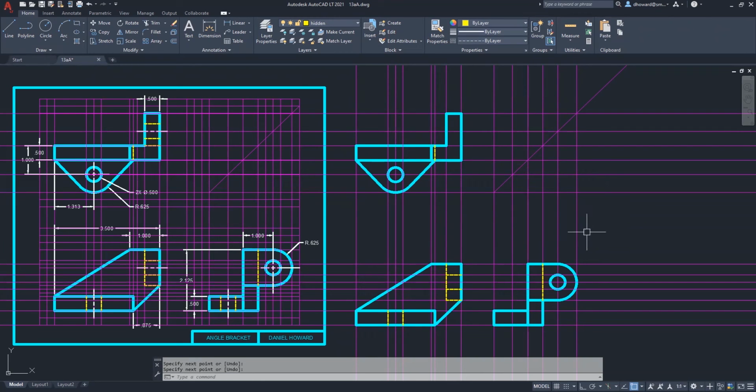Now I'm going to do the center lines. So the thing with these center lines is that normally I would offset the circle 1/4 of an inch like I do everything. But this edge and this edge are 1/4 of an inch away, and the center lines will make contact with that perfectly, and it will appear as though there's some sort of feature there.